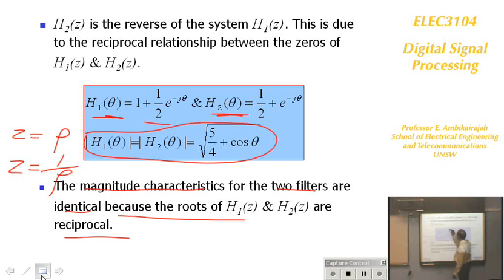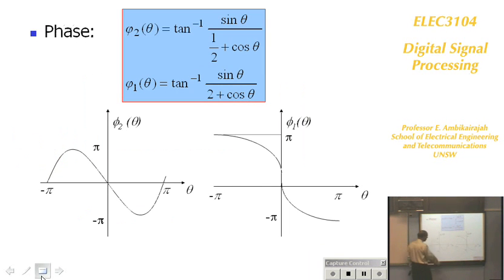If you work out the phase from here, which you know how to do, if you write a MATLAB code, it shows you the phase, and if you plot that, you will see here on the next line, basically for the filter 1, this is phi 1, by the way, I think there's an error here, and this is phi 2. You will find for phase 1, for the first filter, this is your phase change. It starts from 0 and ends at 0. And for the second filter, the phase change is 0 and then pi here, at that point.